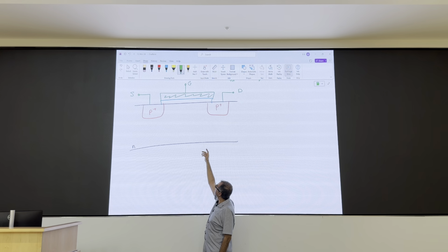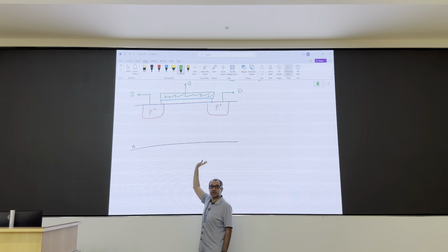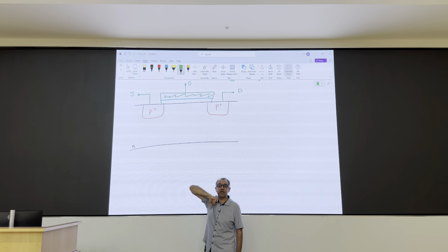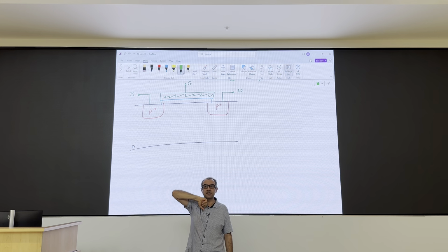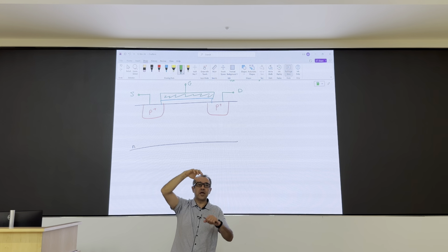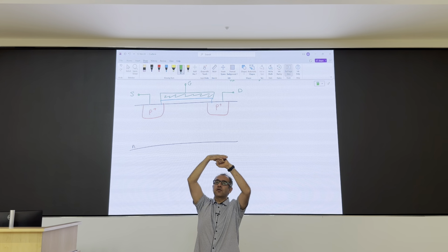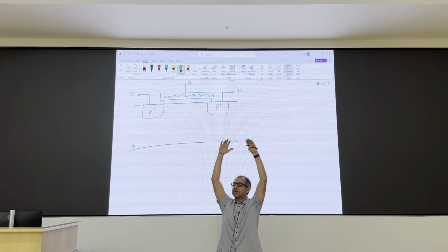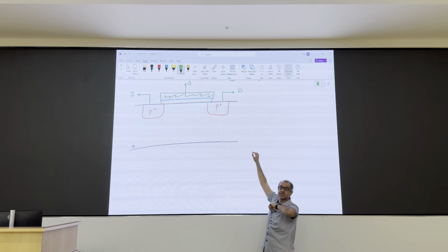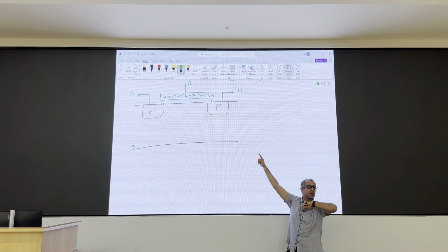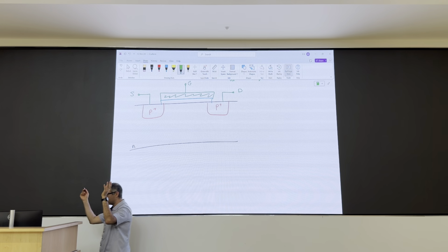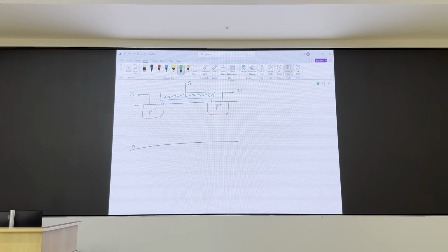So what I need to do is attract holes to the surface. To attract holes to the surface, I need to apply negative voltage, because holes are positive charge carriers, right? So I apply a negative gate voltage, make it large enough so that you have a lot of holes at the surface, and you create a channel between the P regions of drain and source. And the rest of the story is the same, equations are the same, everything is basically simple.